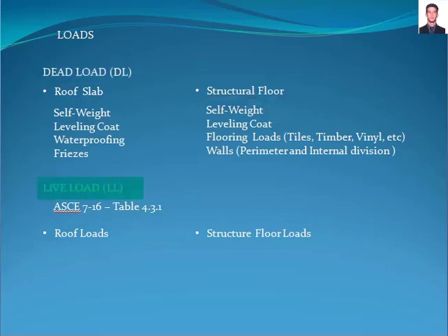Live load definition. Live loads are those that are produced by the use and occupancy of the building, persons or equipment, that don't include construction or environmental loads, and shall be determined by Table 4.3.1 of the American Society of Civil Engineers in accordance with the occupancy or use.